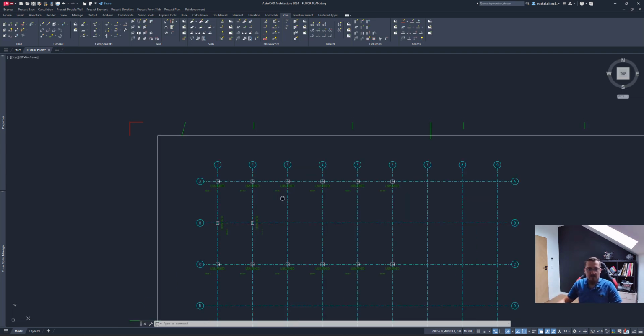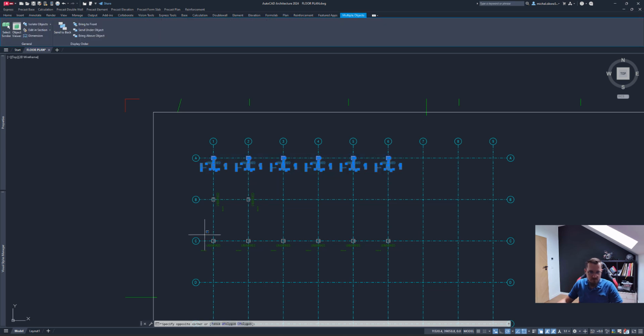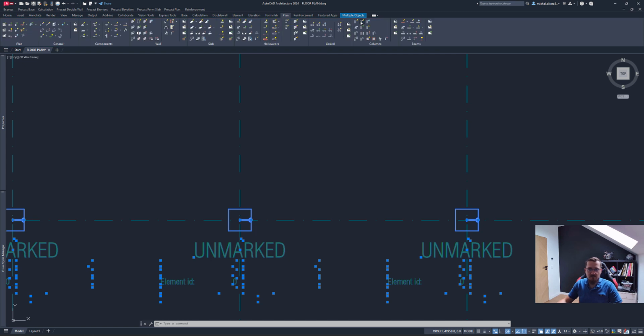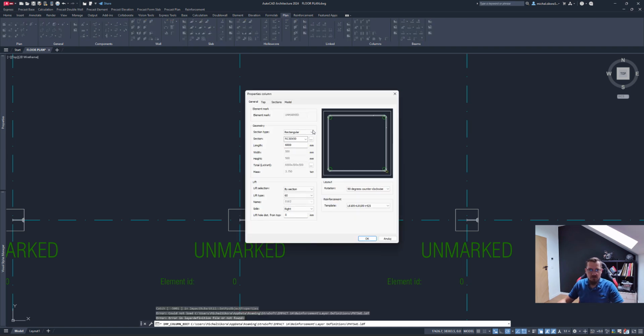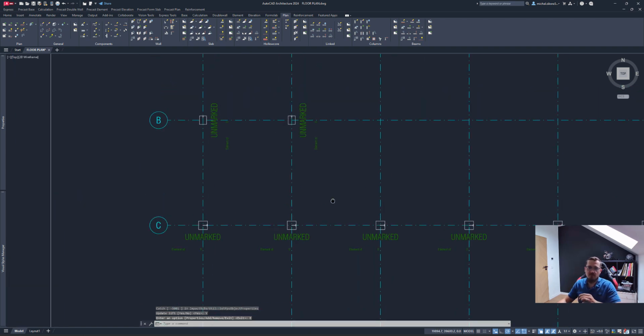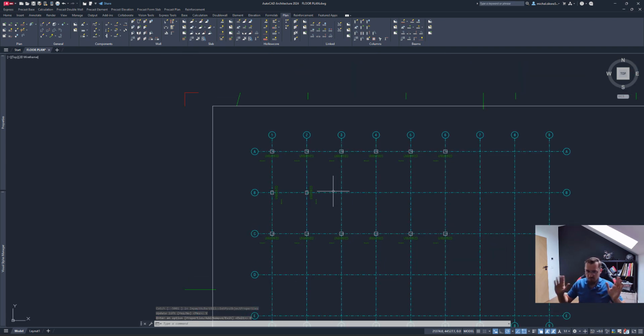What I'll do now is I'm going to select the columns in question, so those 500 by 500. I can either go back to plan and click on edit columns, or I can just double click after selecting those and get back to that. And you can immediately see that we have our preview. It will take a little bit to load on that preview of the template of reinforcement that we have. Just maybe switch back and forth. Yep, and that loaded. And that's it. I can save that, accept that, update lifts. And now this reinforcement template has been applied to our columns.